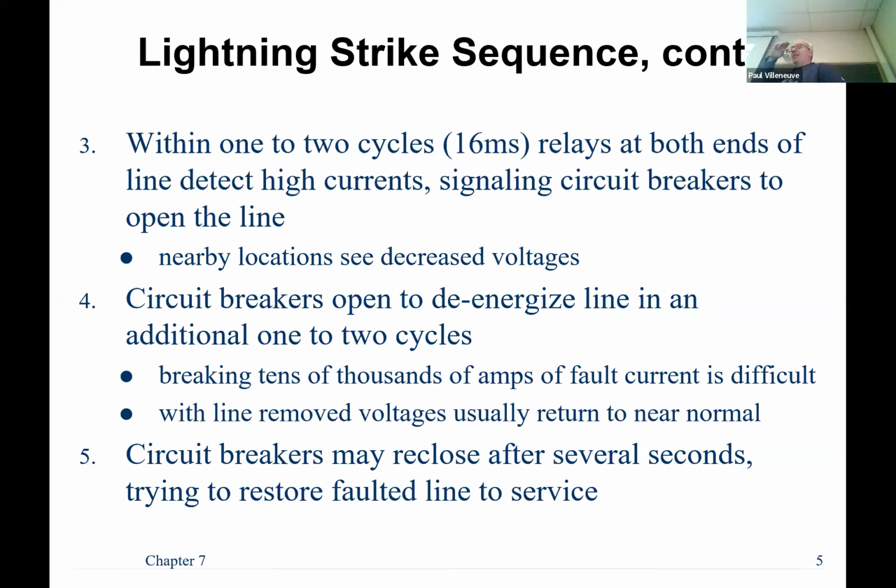You can flick it on and off. But if you've been in your electrical panel in your house or your dorm room, to flip it open, it actually takes a little bit of real pressure to get that open, right? Because there's a lot more spring tension in the breakers in your panel than over here. That's just a basic open close, but that's only interrupting 15 amps. Whereas the breakers in your house are all designed to interrupt at least 10,000 amps for fault conditions.